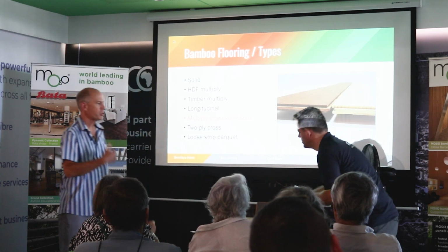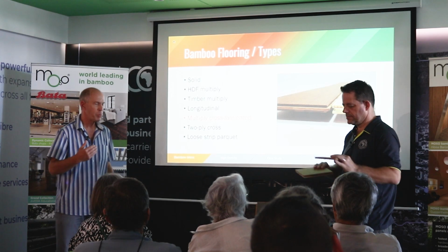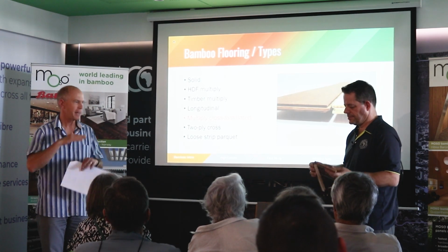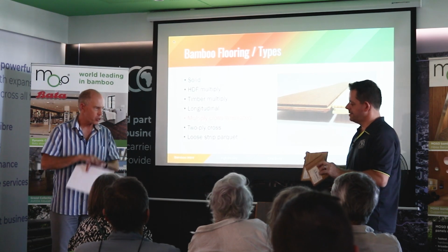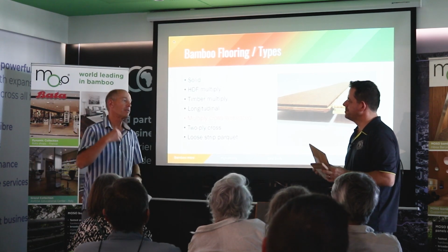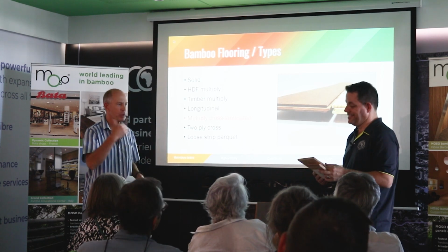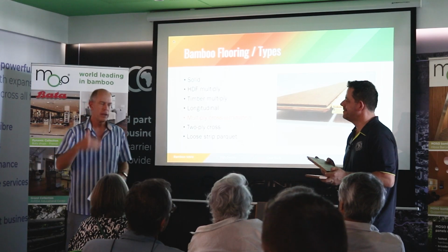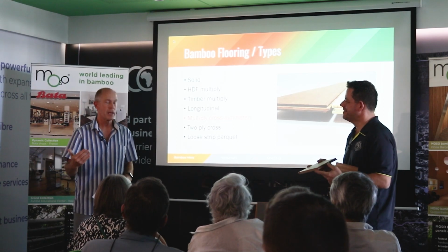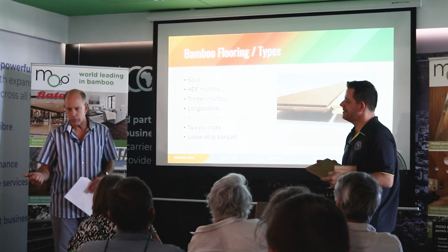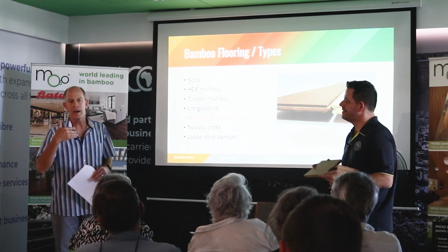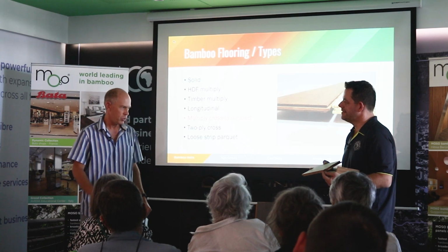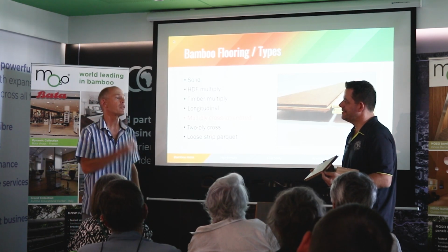So this is also 100% bamboo, but the same principle as engineered flooring. It's got 3 layers and they're cross-laminated, which gives greater strength and greater stability. It's available either with a click joint or with tongue and groove. So again, it can be installed floating, glue down, or on joists, depending upon the thickness of the flooring, the subfloor, the usage. So you've got to take into account all those factors, but it's the most versatile flooring.